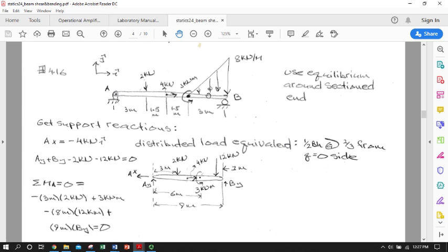So we will apply those same relationships between distributed load, shear, bending, putting a cut section of the beam. It's going to be a lengthening section, so we're going to start with the left-hand side being very small, and it's going to grow and grow and grow until it's the whole beam. But we're going to have 4 different distinct areas of concern, and we are going to use those areas evaluated at the right-handmost limits as the starting points for the left-handmost limit of the next section.